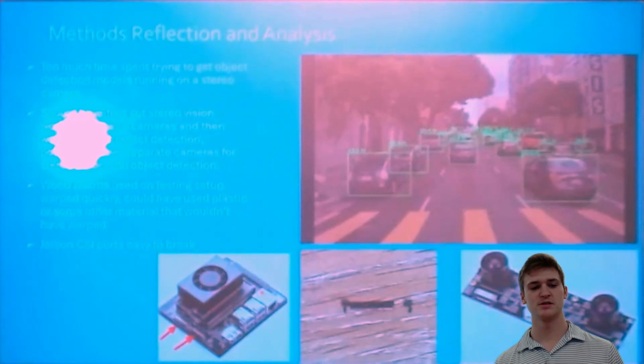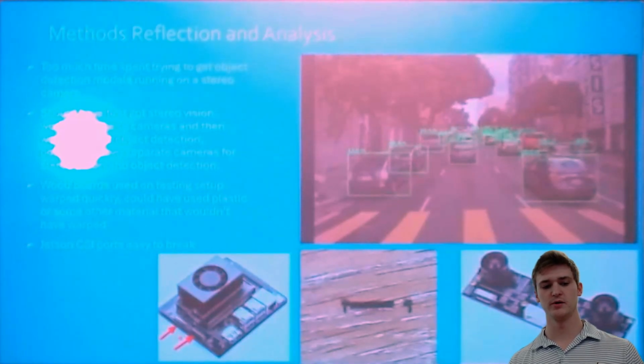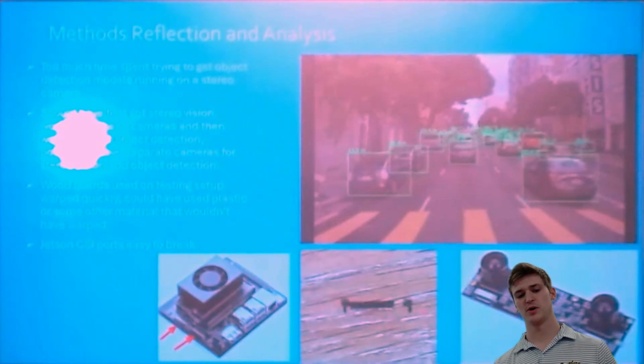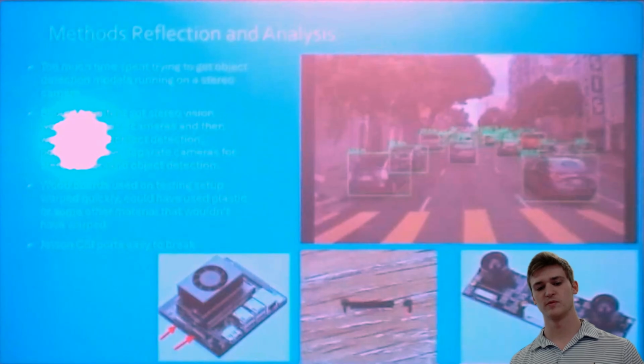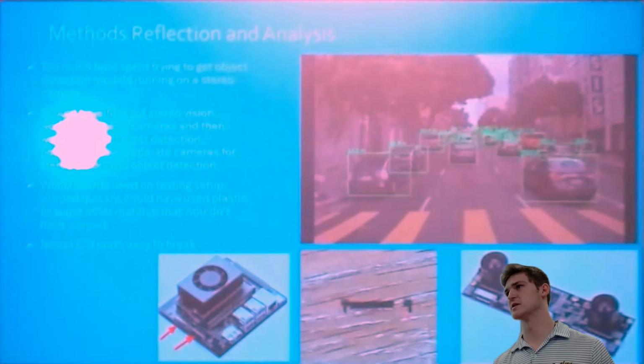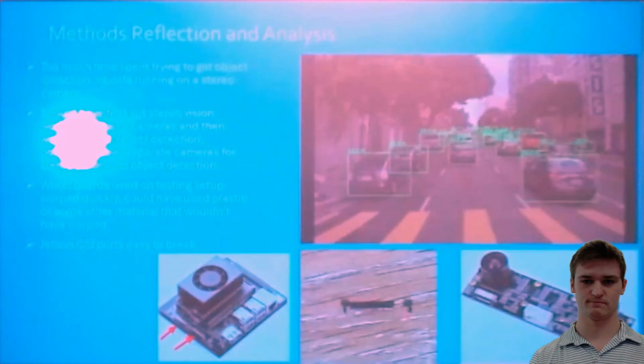And then the Jetson CSI ports are really easy to break. You can see them down here, for use with the stereo vision cameras. The little insert pin here, the sides of it with a clip, can break really easily, and then you can't use that CSI port anymore.